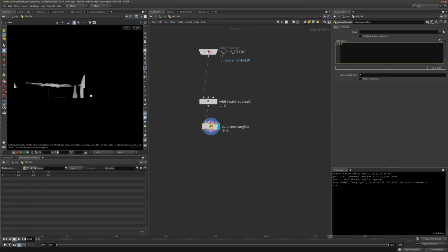And again, this could be adjusted inside the flip solver as well, but I'm trying to minimize the disk size footprint as well. So I'm just going to make everything as optimized as possible, so it doesn't bloat in the end. So here I'm saying anything deeper than 4 meters, emit is equal to 0. Okay. And now that's too much. So oh, maybe -4, sorry. Yes, -4 meters. So we did a little bit of culling there.